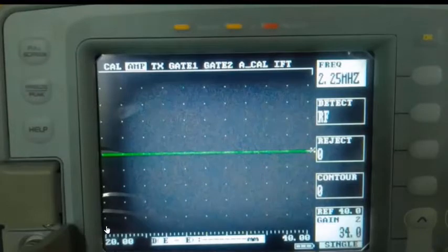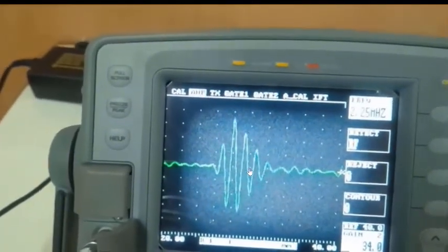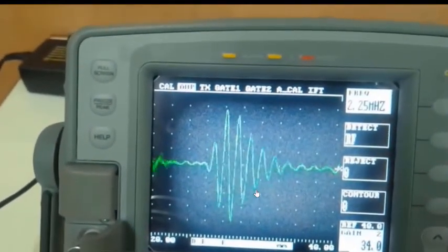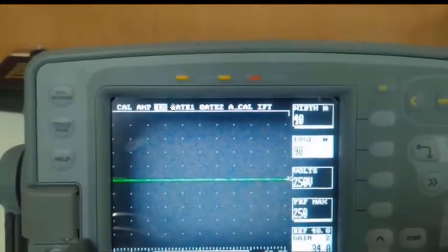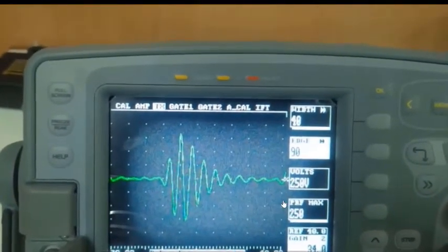And now we are going to carry out the calibration. So keep the transducer on the sample of given thickness, and first you get a proper shape for the echo. That can be done by controlling two press buttons over here from this TX menu, in this particular model.